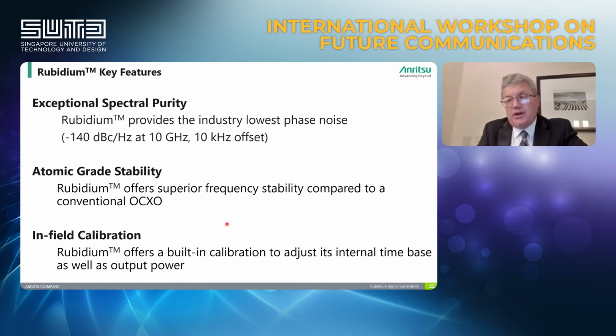Of course, it has many other features and options such as different modulation formats such as amplitude, frequency, phase, pulse modulations, and their combinations like chirp modulations to simulate different standards and support many different modulation schemes.